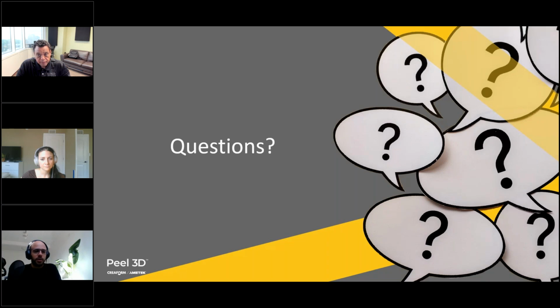Sure. So actually, when working with ExactFlat, we don't really need an extremely high resolution for just scanning the geometry. The reason being is that we don't really want to overload the software with way too many vertices. So depending on the size of the object, we'll choose our resolution settings based on that. So let's say you're flattening something the size of a helmet, or just something with a very small surface area; in that case, you may want to use a resolution of around 1 millimeter.